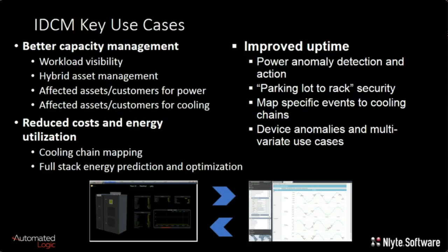Reduce costs and energy utilization. Why do we run our chiller systems on a Sunday morning the same way as we do on a Tuesday morning? Very different workloads. If the building had insight into the workloads, we're able to tailor that critical infrastructure. We're able to tailor the set points and all the other factors that we have control over to much better match the demand with what the building itself needs to provide.